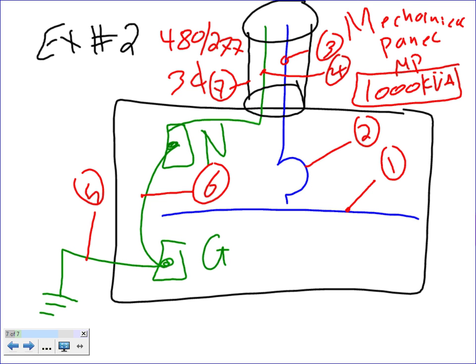Any question, guys? I want to remind you, it's not a service, it's a panel. So what would that give you, Spencer? There is no grounding electrode conductor in it, and no system bonding jumper. Well, why am I putting a system bonding jumper in then? Oh, that would defeat the purpose. Let me just retract, guys, and make a service.